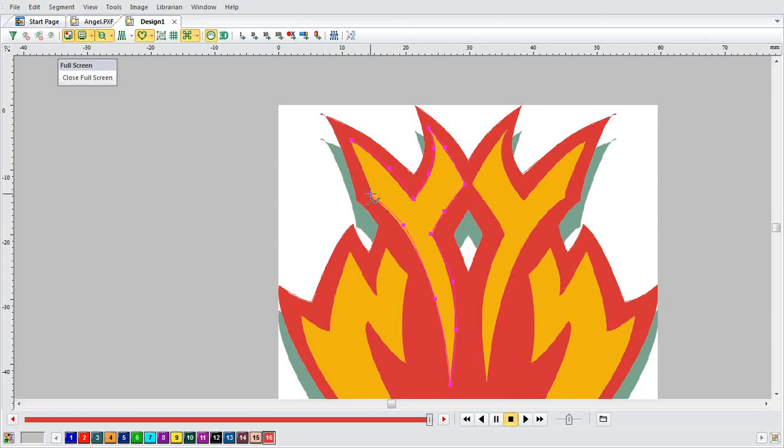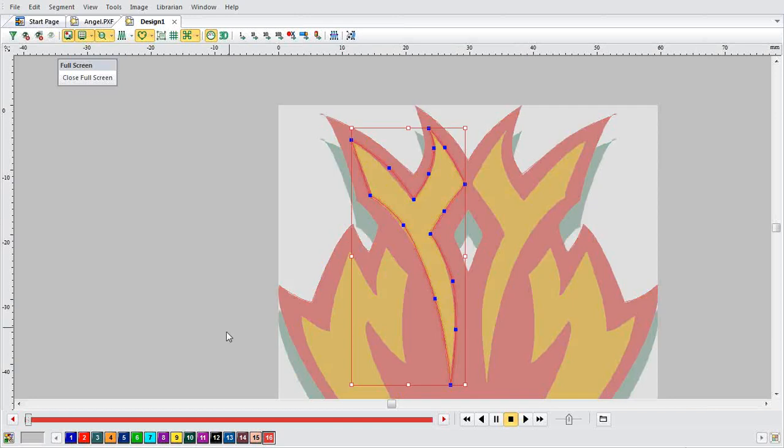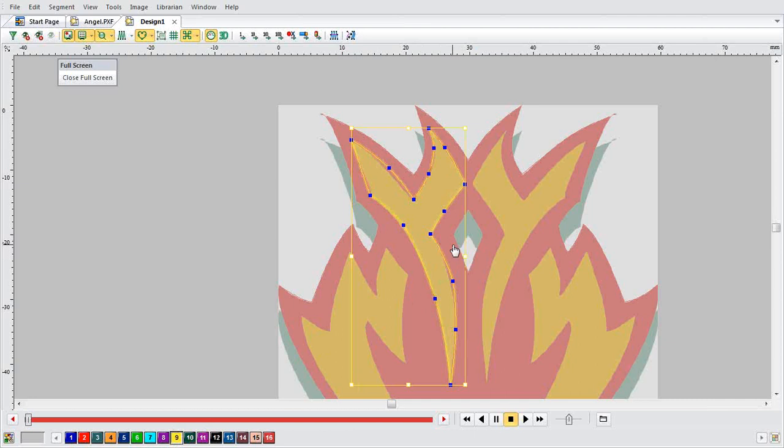Let's close this with the button O. And now, let us slice it. The virtual slice shortcut is letter U. I'm slicing here. I'm adding my directions. Here you are.